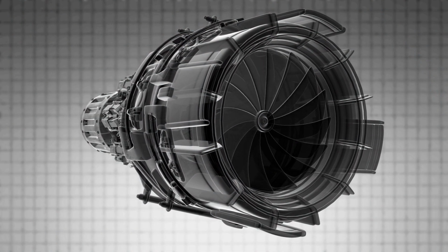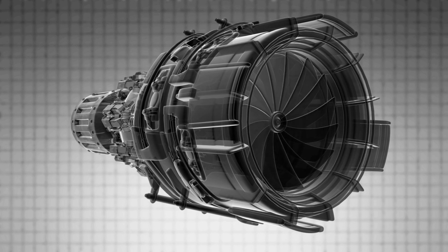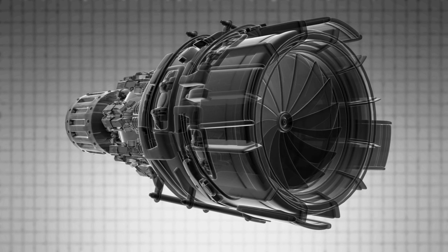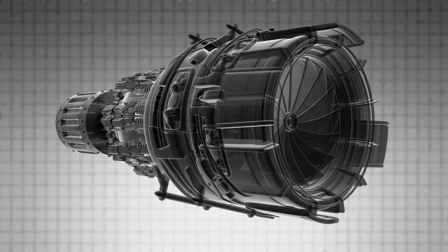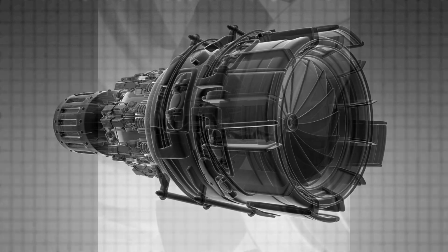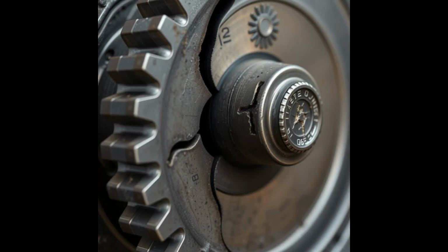Appearance. When torsional stress is present, it often manifests as shear stress along the material. In cylindrical parts like shafts, the stress increases as you move farther from the center axis, meaning the outer edges bear the highest stress levels. Over time, if torsional stress exceeds the material's capacity, it can lead to the development of small cracks, often at a 45-degree angle to the axis.